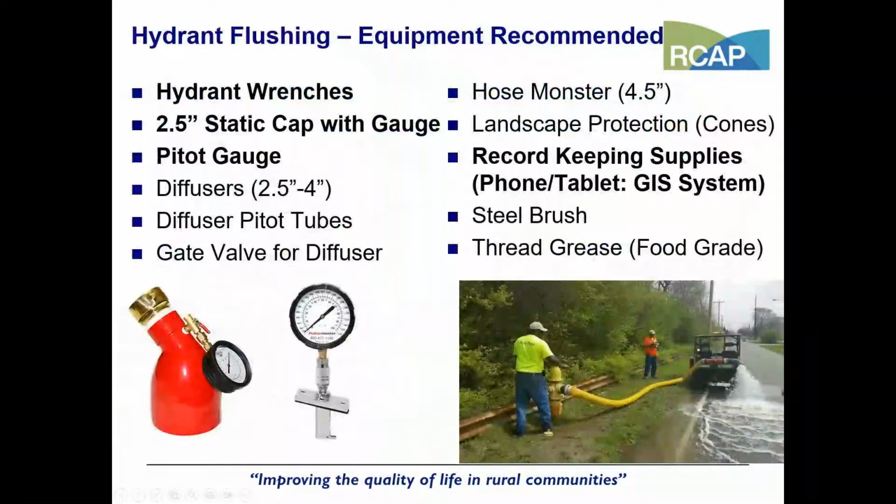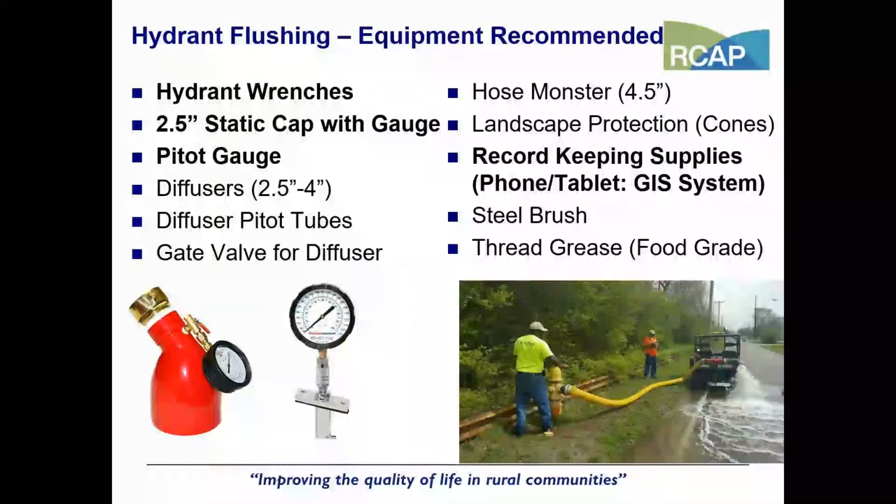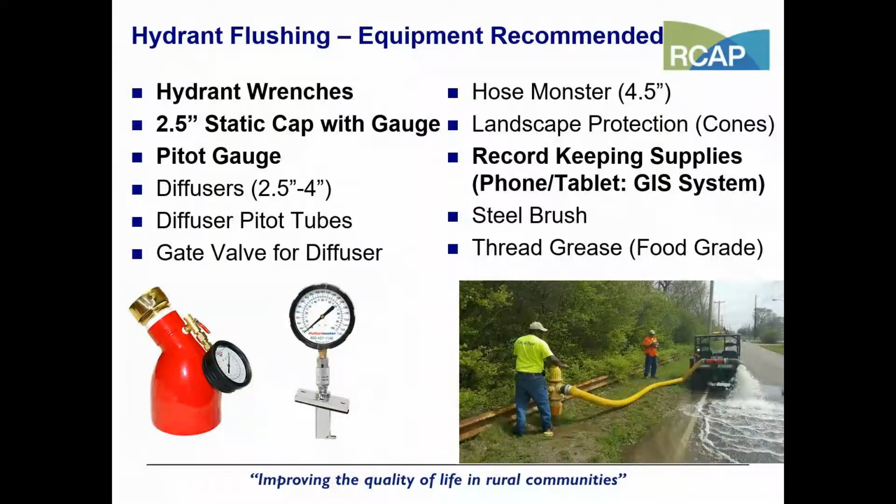Some systems don't have the best design to do that, but if you can find spots in your system for unidirectional, don't just think of it as a binary, like you're either doing it completely or you're not. There's always improvement. I will say though, if you do unidirectional flushing incorrectly, it can really keep all that sediment knocked around in different spots. So it is important to make sure you have the pressure ratings to actually do so.